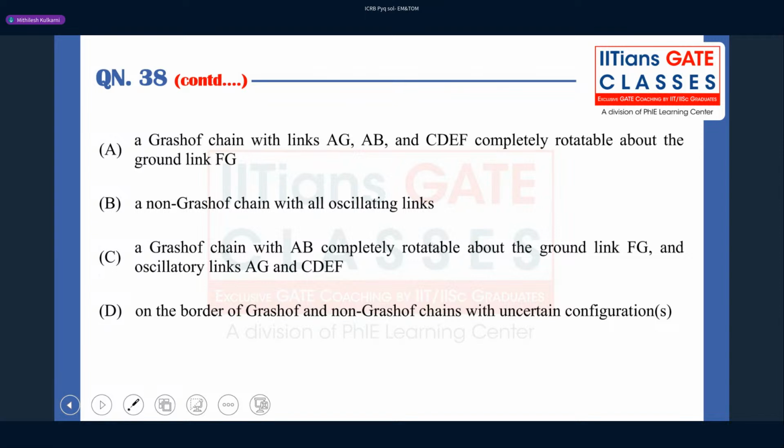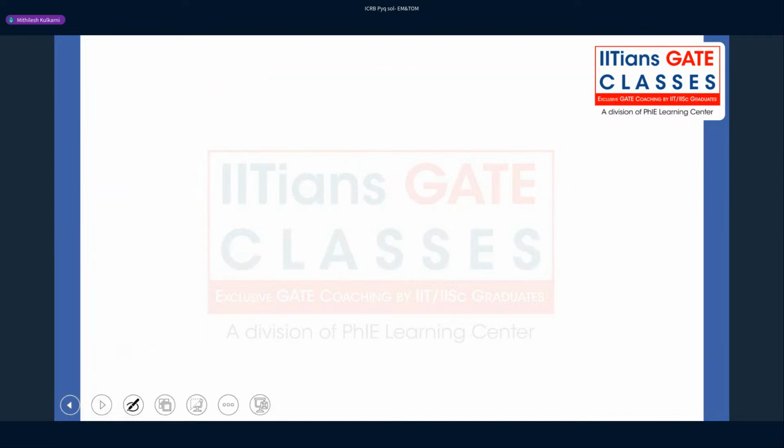So they are talking about what kind of mechanism this is, whether it's a double crank, or let's say Grashof, non-Grashof, and so on. Basically it's a Grashof chain or a non-Grashof chain. These are the kinds of options we have. So let's first talk about what Grashof's law says. Write down Grashof's law. Grashof's law states that in a 4-bar chain mechanism, there will be at least one revolving link if the length of the shortest plus longest link is less than or equal to the sum of the other two. So P and Q are the other two, and S and L are the shortest and the longest.